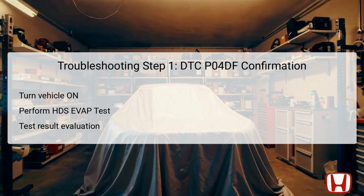The first step in troubleshooting DTC P04DF requires confirming the fault. Start by turning the vehicle ignition to the on position without the engine running. Following this, utilize the Honda Diagnostic System (HDS) to conduct the EVAP leak check module test. This test should provide critical data regarding the health of the EVAP system. Pay close attention to whether the results return as OK or not. A failure here suggests that there is a duplication of the fault, affirming that the EVAP system warrants further inspection.